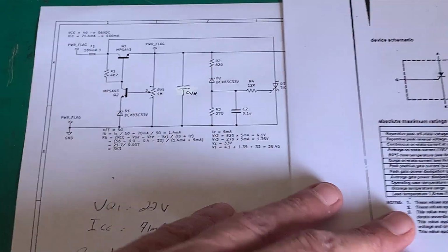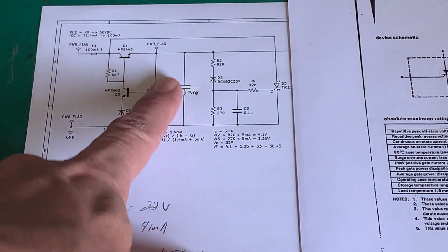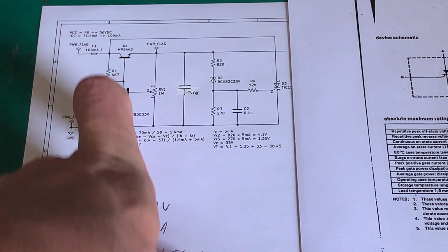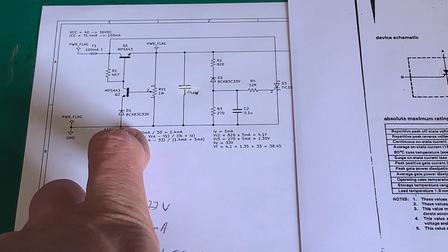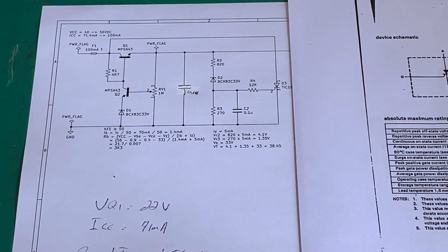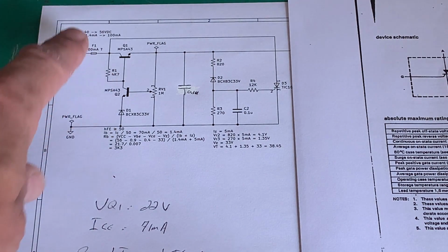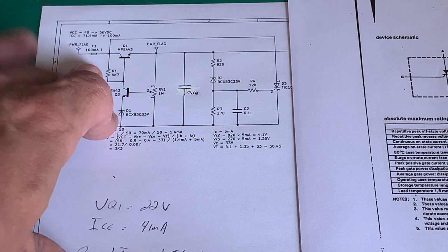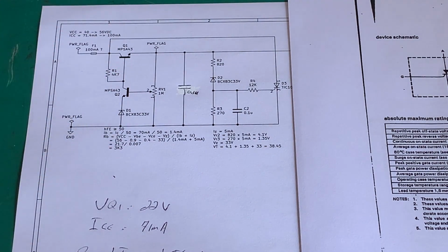So why didn't I just go with a switching regulator here? Well, it defeats the object. If we can use the building blocks, why not? A switching regulator at higher voltage is quite a bit more expensive, so we'll do the trade-off. We'll do it this way and see what power we're losing. I'm not worried about milliwatts on a huge battery bank. I mean, that's really not crucial to me, because the circuit we're designing is only going to pull 4 watts.